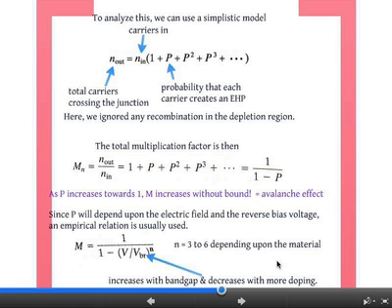Now, if this distance is very large, the applied field will be small, right? Which means that the excess kinetic energy that the electrons have gained is small as well. So in order to increase the probability that this impact ionization happens and creates an electron-hole pair, you want to make this smaller. In other words, you want to increase this doping. It's another way to control it.